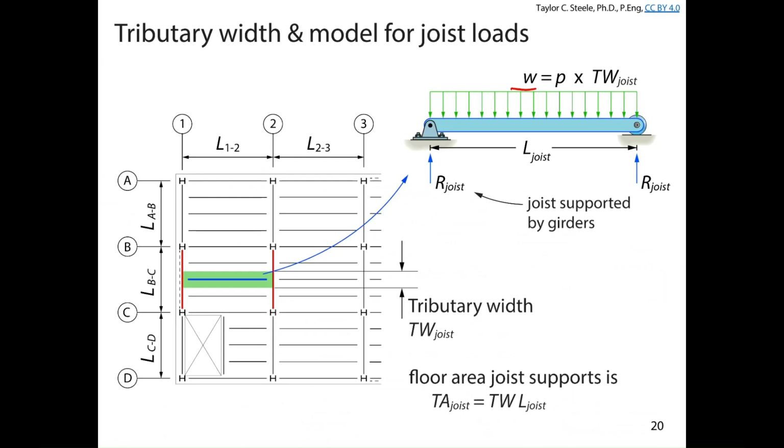But if you take that load and average it out over the floor area, we essentially treat it as if it's a uniform load, and we usually use units of kilopascals to talk about stress acting on a floor. It's kind of like when you did soil mechanics, you had equivalent stress, you calculate H times the density to give you a stress acting at that level. We've got a stress or a uniformly distributed load acting over the floor system, and we need to take those loads down through the structural elements.